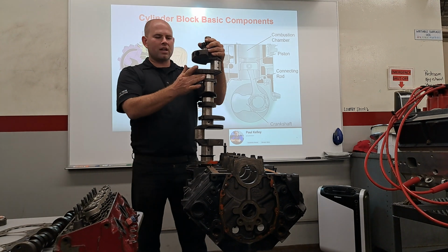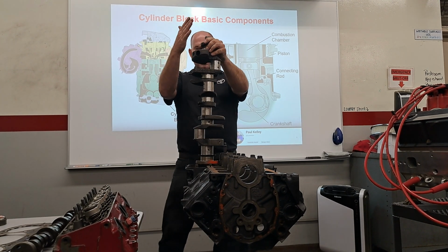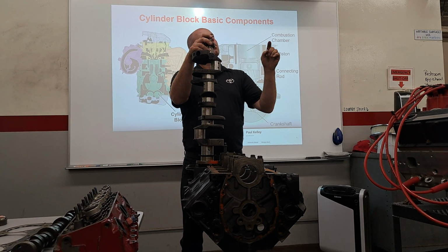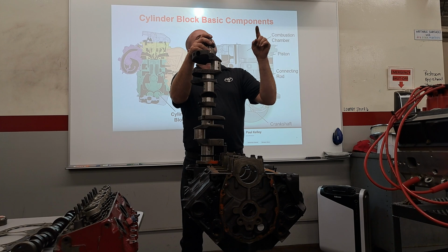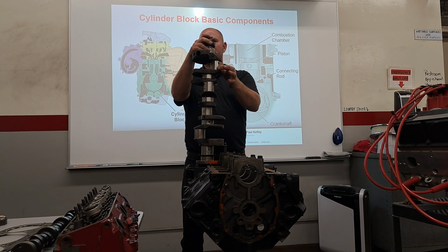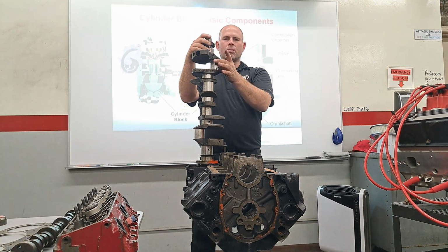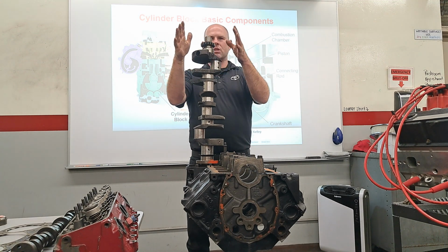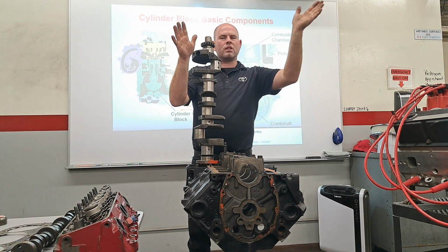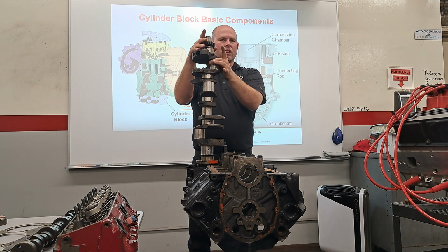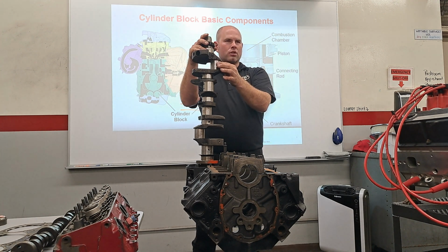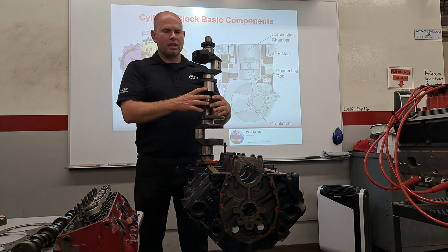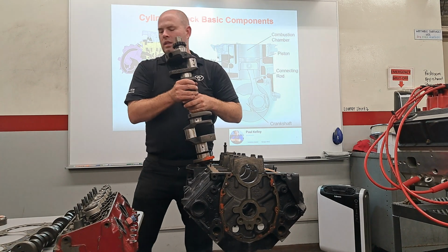Right? So now, this was number 1, but actually it also shares with 2. Yeah, 1 and 2 are actually on this journal right here. On a 4-cylinder, typically it's 1 and 2 and 3 and 4. But on a V8, because they bring the 2 cylinders together, cylinder 1's in the front and 2's in the front on the other side. They both actually share this journal. So this is a combined journal right here. Now we would need to do some more measurement to really check this crankshaft out, but I think you guys get the idea for now, because I got some better pictures later.